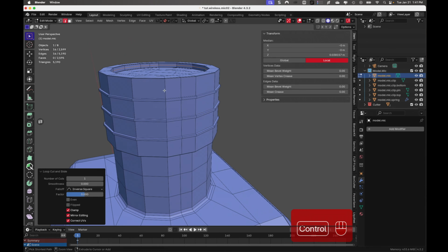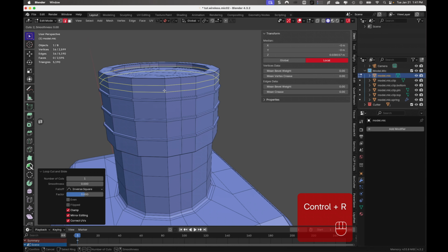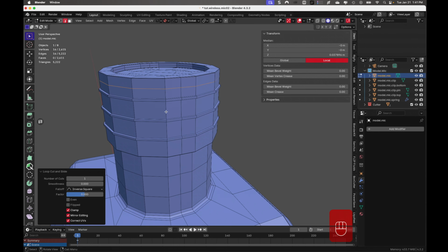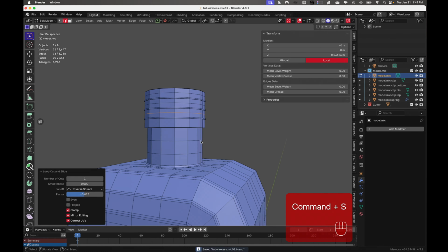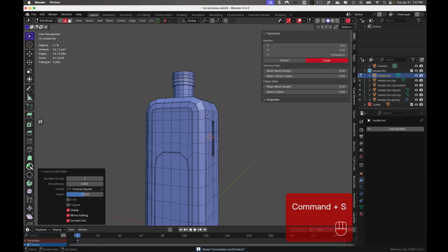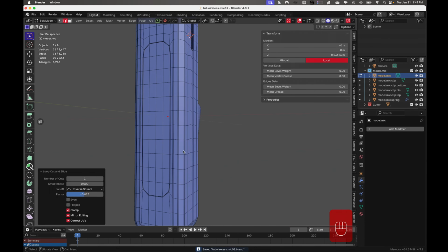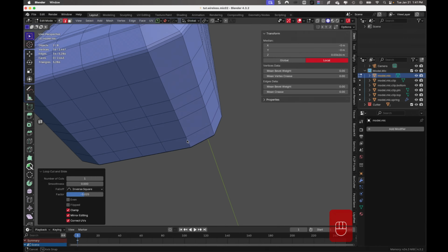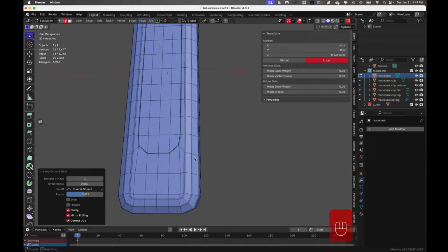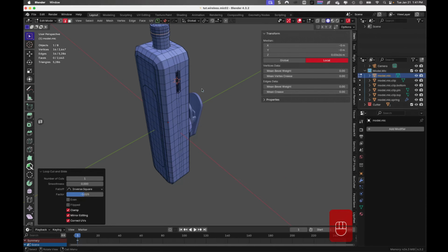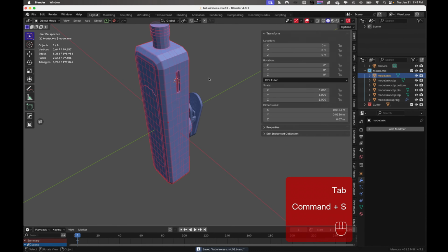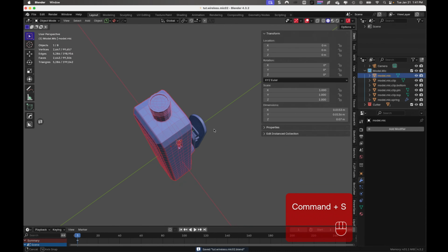Then we'll put a little support loop here, and here, and here. The only reason why I'm doing that is I'm trying to get roughly even size faces in certain parts of the model. They don't need to be even faces everywhere in this case, but in certain parts I want them fairly even, so you have good distribution of geometry. It just makes the model cleaner and lessens the chances of you having weird artifacts, which you've seen in this video a couple times when I model stuff.